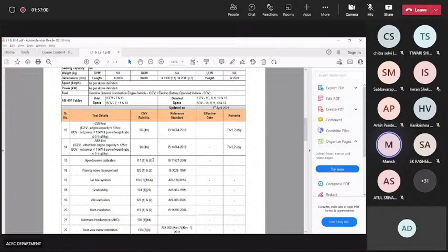Ola, Ather, TVS, Honda have WMI numbers given to them by SAE. Using that WMI, the 17-digit chassis number has to be created, and the definition of the chassis number created using the WMI has to be submitted to ARAI or ICAT, explaining how you are defining your vehicle chassis number.